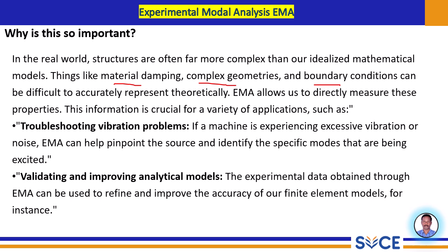So there will be some significant uncertainties in our theoretical calculations. This is where the power of experimental modal analysis shines. Instead of relying solely on potentially inaccurate assumptions, it allows us to directly measure the dynamic characteristics of the actual physical structures.